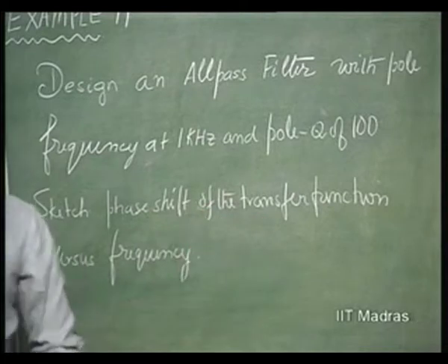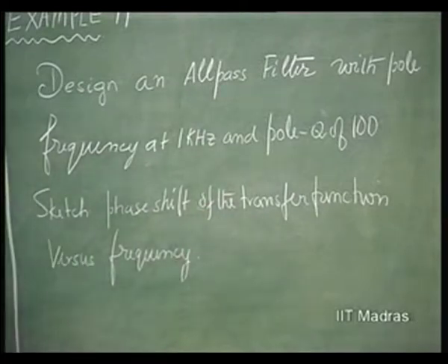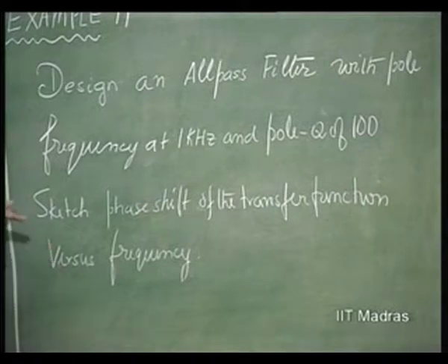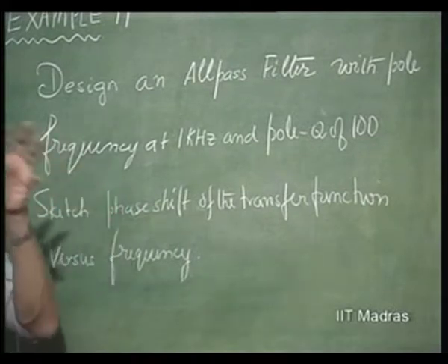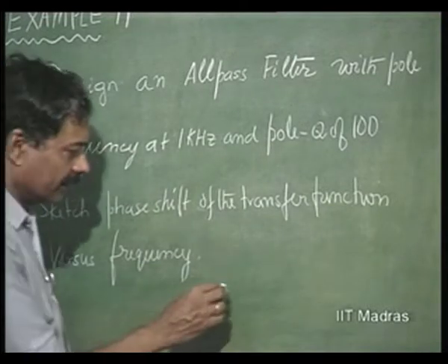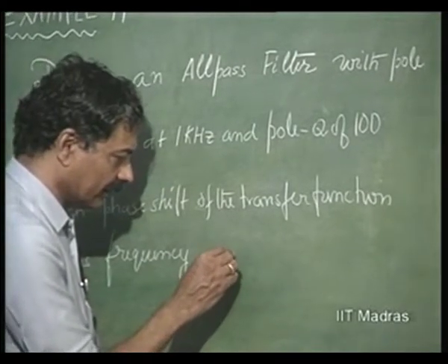Here it is primarily used for obtaining phase shift variation with respect to frequency. So, we will see how such a network which passes all the frequencies without any attenuation or with same amount of attenuation or amplification, but will subject each frequency component to a certain phase shift. So, such a transfer function, second order transfer function will look like this.